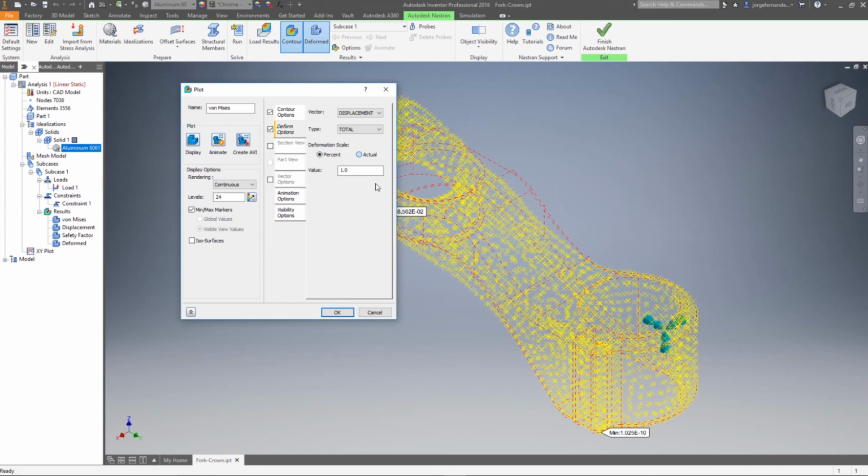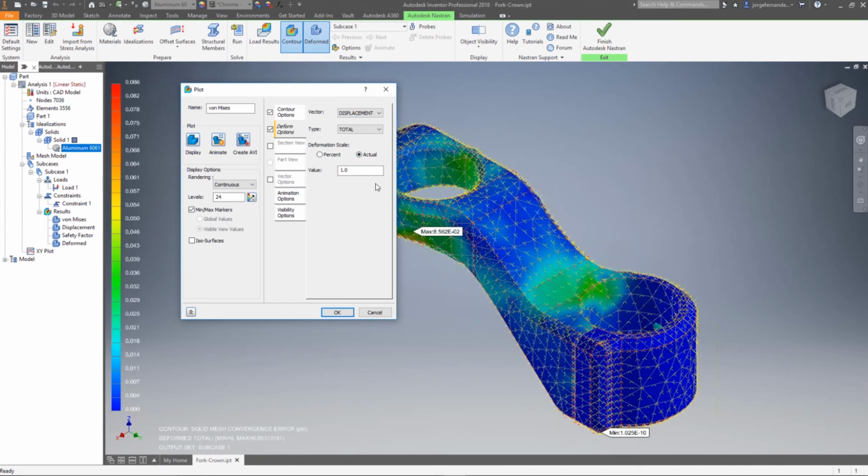That's going to be important when you're looking at the full assembly and trying to see the actual displacement. If it's 0.01, it's not going to be so drastic, but as that starts to grow, this is going to be even more important. So that load doesn't make this fork piece super jelly, right? It's just a representation of what's actually happening.